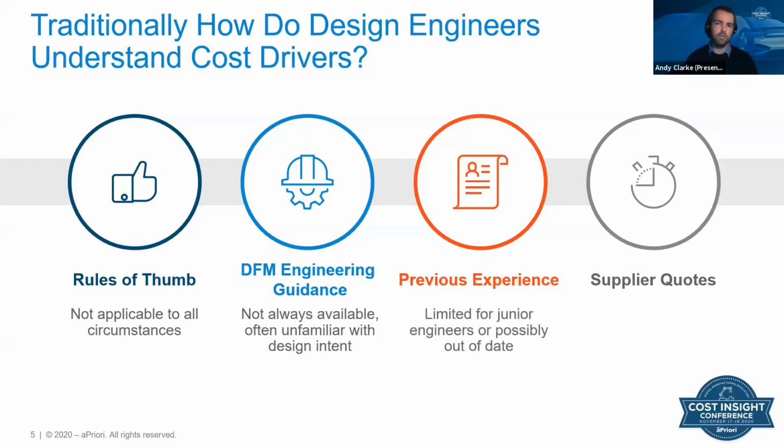And lastly, if you really want a cost for your product and understand the cost once you design it, you can send it to a supplier for a quote. However, there's a risk here with sending development parts to a supplier, especially if you haven't told them that you're not expecting to execute on that RFQ in the near term. The supplier might get upset that you keep sending them parts that you don't end up purchasing. They might give you a no quote.